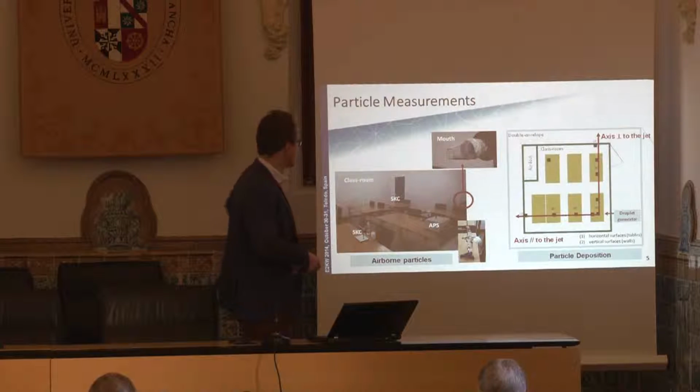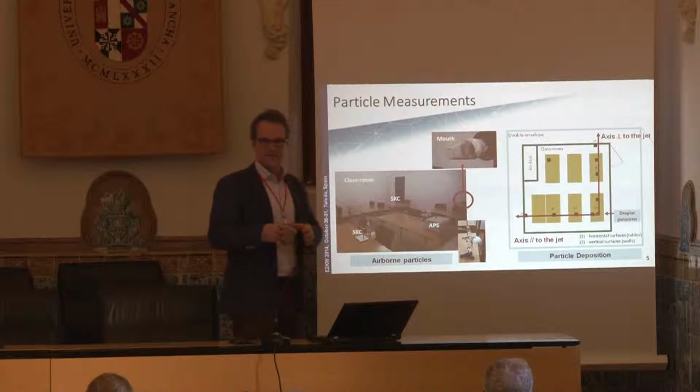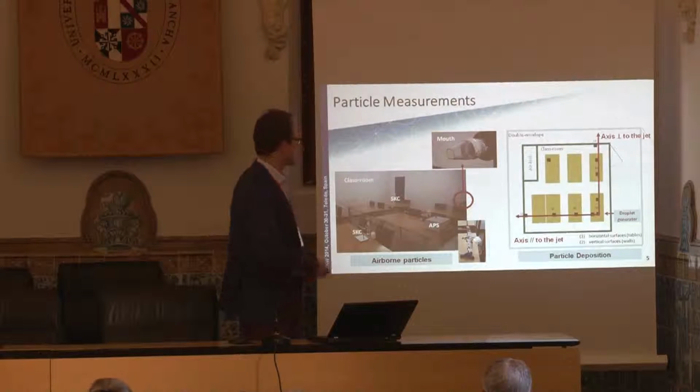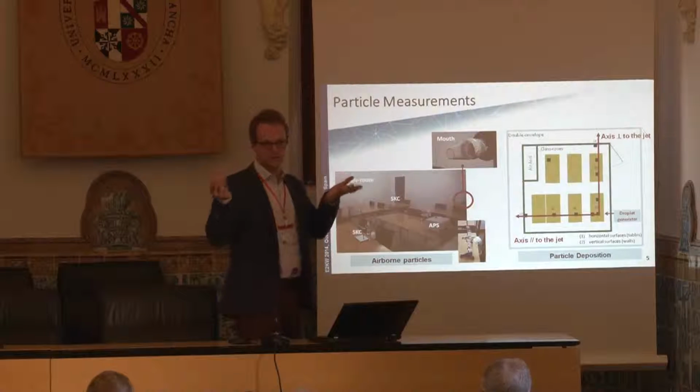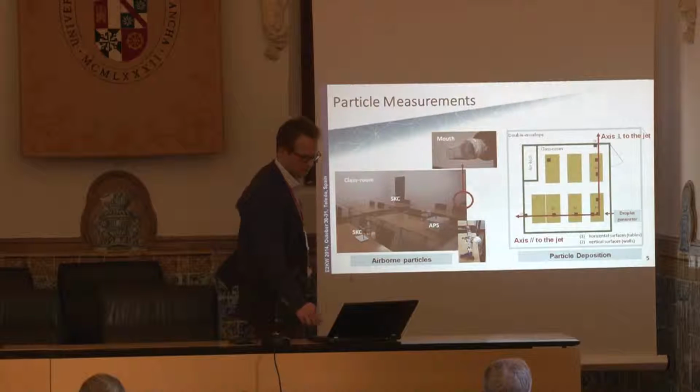The idea here is to show you the room with different equipment to measure the airborne concentration within the room or the particle size distribution within the room. But also here on the right part of the slide, you can see the different tables, and on the tables there are some black squares representing the test surfaces that we use to collect the deposited mass on surfaces. So at the end, we can have an idea of the concentration of particles within the room and the concentration on surfaces, let's say the mass deposition onto the surface.